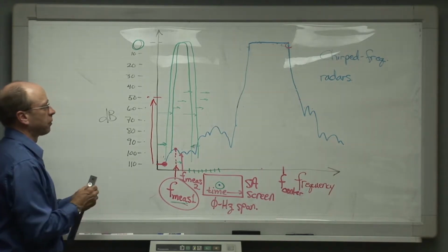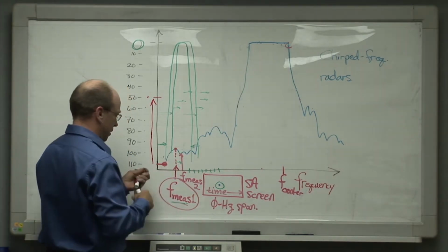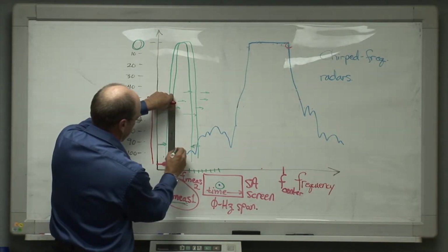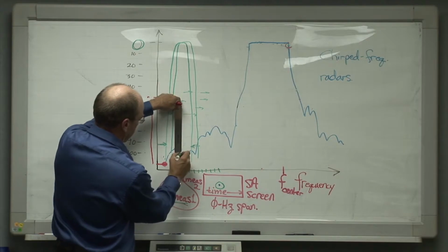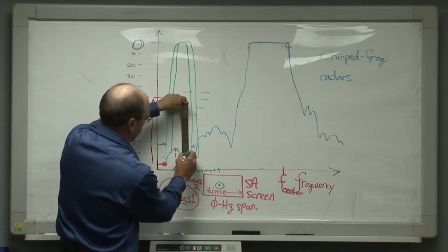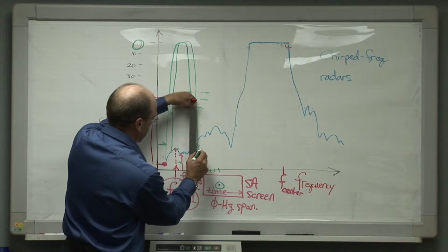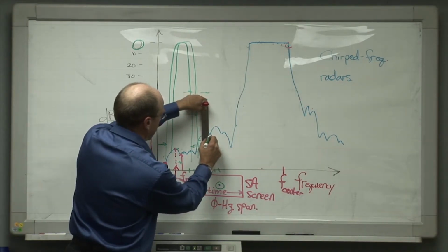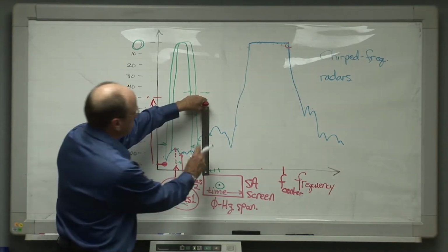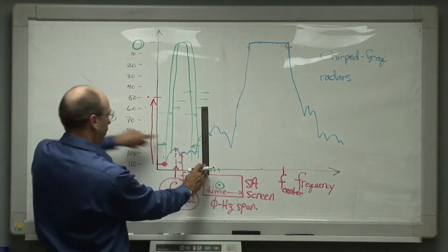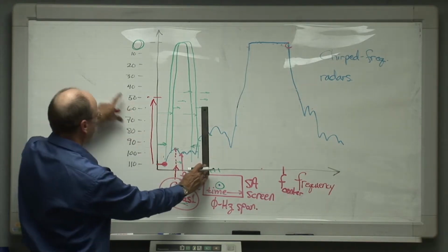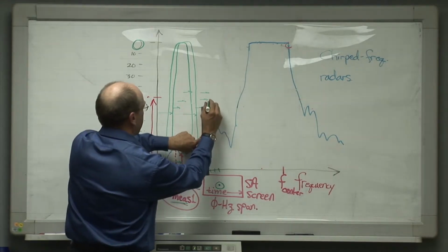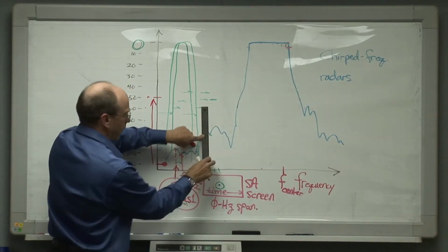And as we do this, what's going to happen here? Well, at first, as we walk our way across from this point right here to this point right here, where we measure that level, and so forth on across, power's getting higher, power's getting higher, power is getting higher, we say, hey, wait a minute, we're starting to really run out of dynamic range at this point. At this point right here, for example, we're down to about 30 dB of dynamic range left before we're going to run out of dynamic range roundabout in here.